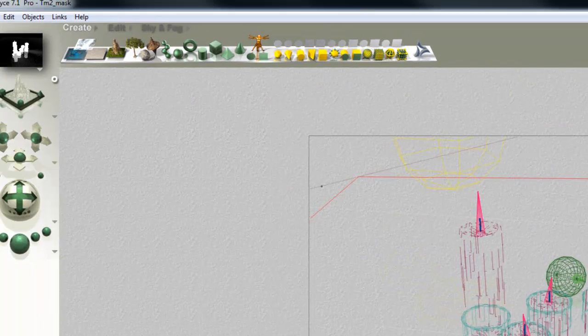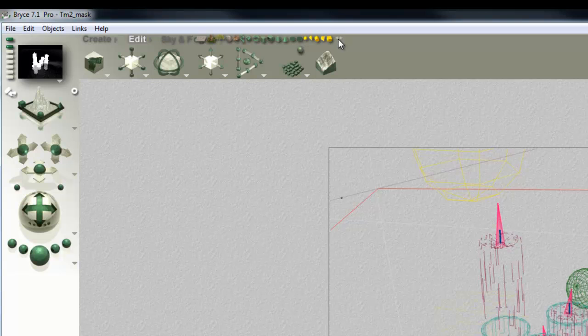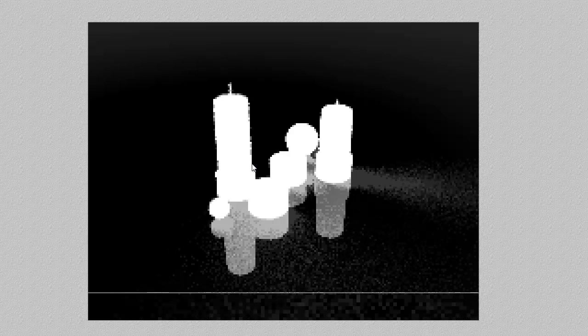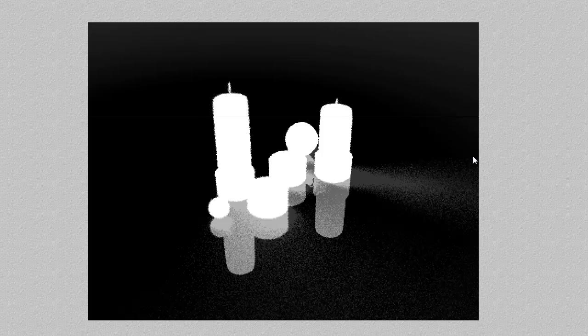I'm going to take this 2D face and convert it into an infinite plane, just so that if that picks up any more light because it's slightly glowing, then it won't create a harsh transition in the background, so it'll be less obvious. So I'll just give that a quick render to make sure there's no obvious problems. So now that's slightly out of focus on that. That should line up with the image that we're going to do, so all those things blur, the blurring matches the blurred image of the other one.